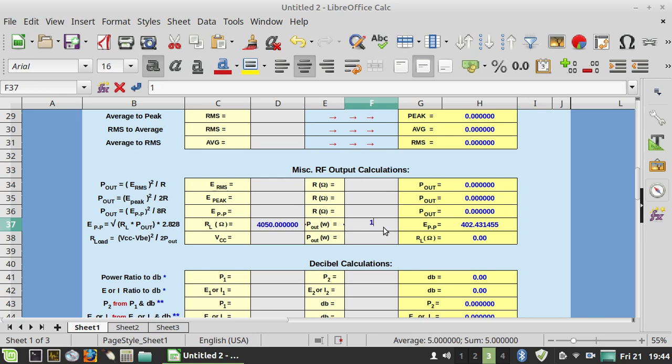What's the voltage at 100 watts? 1.8 kilovolts. Yeah, now I'm thinking I better check my voltage rating of the cap on my unun if I'm going to run it. It's not 1.8 kilovolts. I think it's a 1600 volt cap. It hasn't broken down yet, but it will if I give it time.